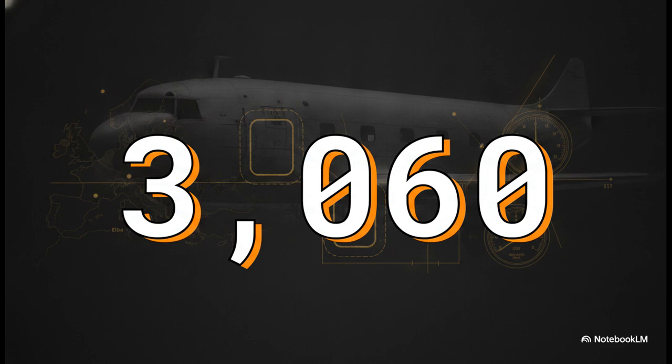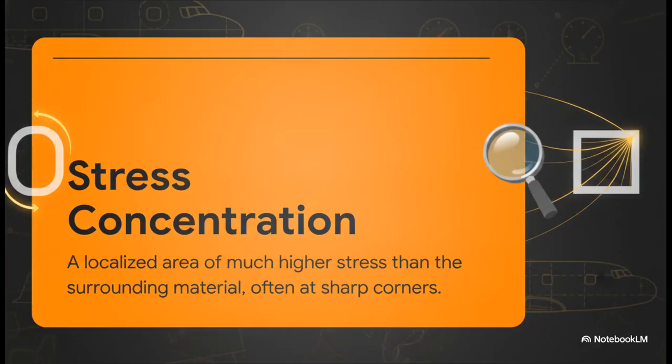and Naples crashes. The technical culprit hiding in the aircraft's design was a phenomenon known as stress concentration. In a pressurized fuselage, structural loads have to physically travel through the aircraft's metal skin. If you have a curved opening, those forces can move smoothly around the edges. It's kind of like water flowing easily around a smooth stone in a river. But sharp, squarish corners behave very differently. At a sharp 90-degree corner, the stress can't flow smoothly. It piles up and becomes intensely concentrated in a very small area.